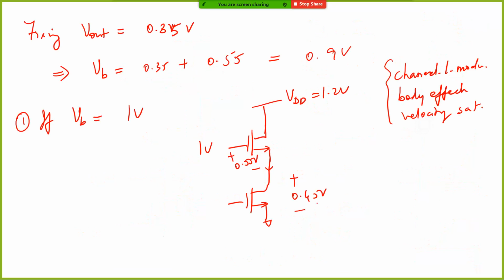So instead of saying that the Vout sets the current, when you're designing the circuit, what happens is you set the bias voltage and design the transistor in such a way that it will take only a certain amount of VGS, and the rest it will push across your next transistor. So this is how it works. Even in op amps, this is the concept that happens.